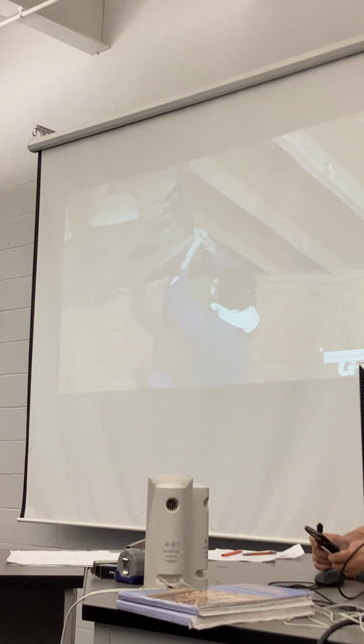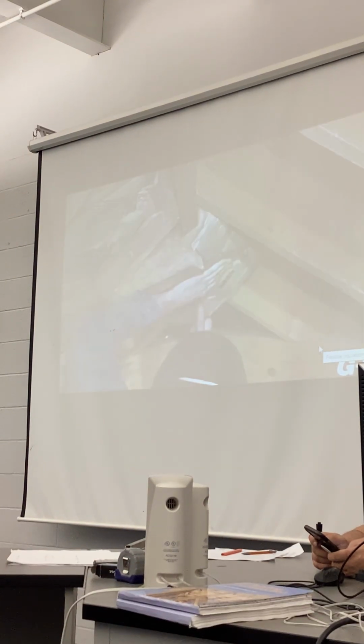To cut fiberglass insulation to size, cut the paper facing with your razor knife, being careful not to cut yourself. Then tear the pieces apart.